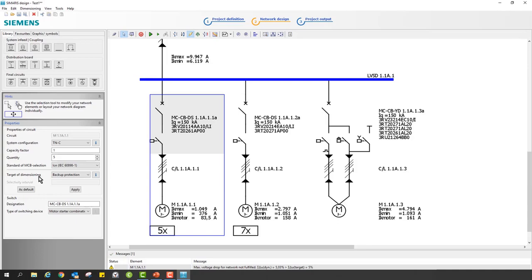This is something really important. According to the IEC 60204 and 61439 standards, I can actually disconnect a non-stationary load that has no direct contact with people, with personnel, for up to 5 seconds. Take this into account also for your design. But as you can see, this is done by itself.